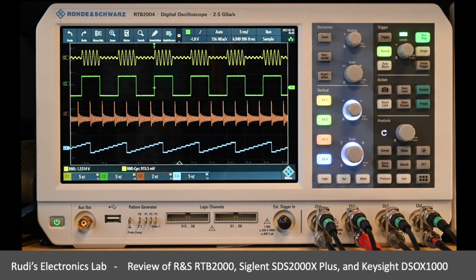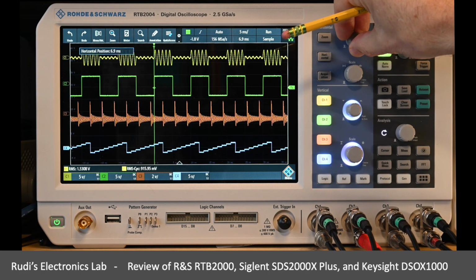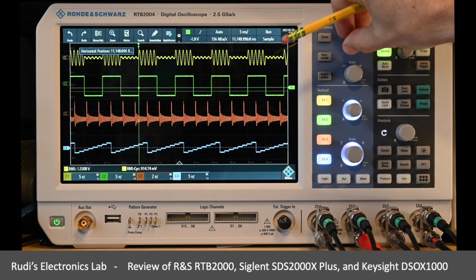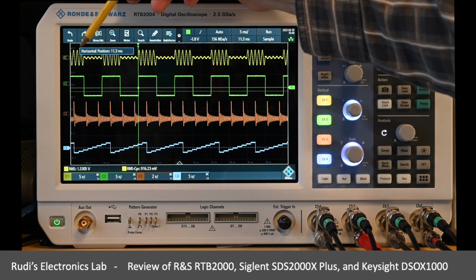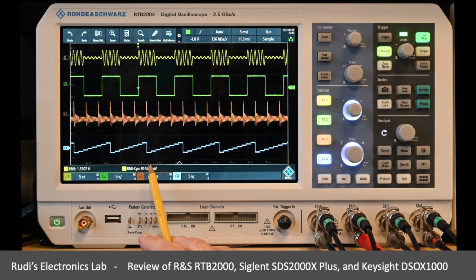In order to check if that is right, I can just move around the waveform using the time-base settings. I'm going here and I would expect it picks up this waveform here and the value will be high. No way, it stays at 0.9 millivolts only. And I expect it to be bigger than this, which is the average. I would expect it to go close to 2 or something.